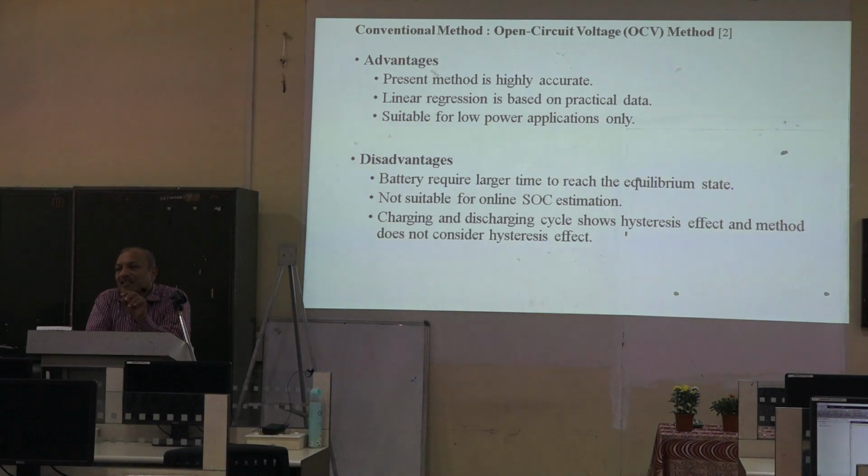If you are not able to identify the equilibrium state within a certain time, online SOC estimation or charge estimation is not possible accurately with open circuit voltage.